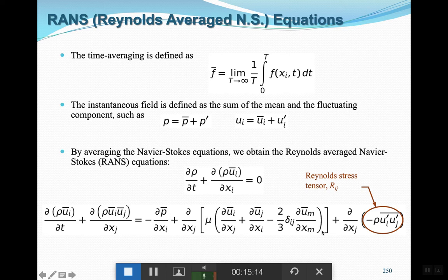to the Navier-Stokes equation, meaning substituting the parameters with the decomposed versions of them, then averaging them, every parameter, as you see here, would be in terms of average velocities and average pressures, except the last one, except this parameter, which still remains in terms of the ui primes and uj primes, in terms of the fluctuations.